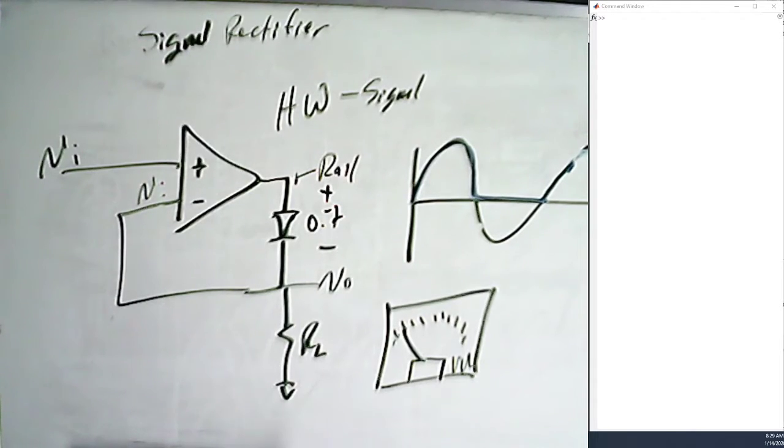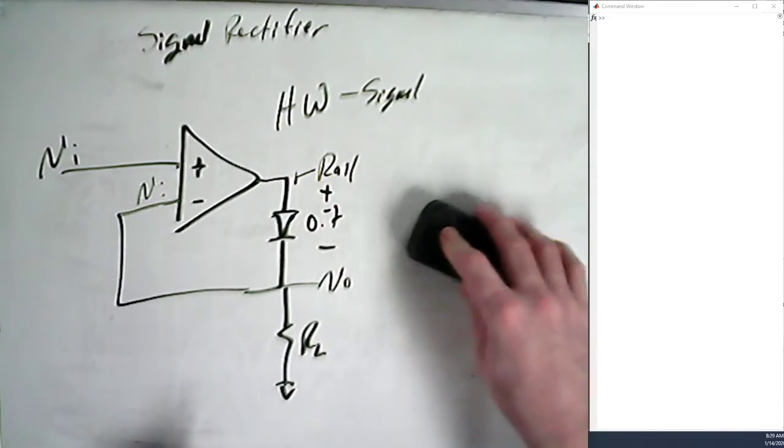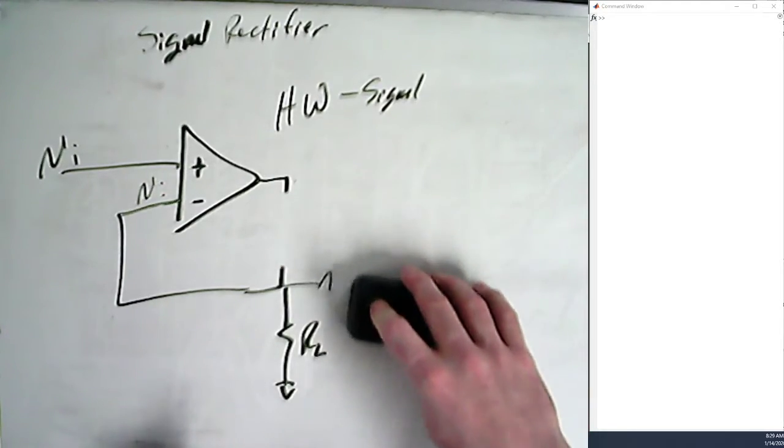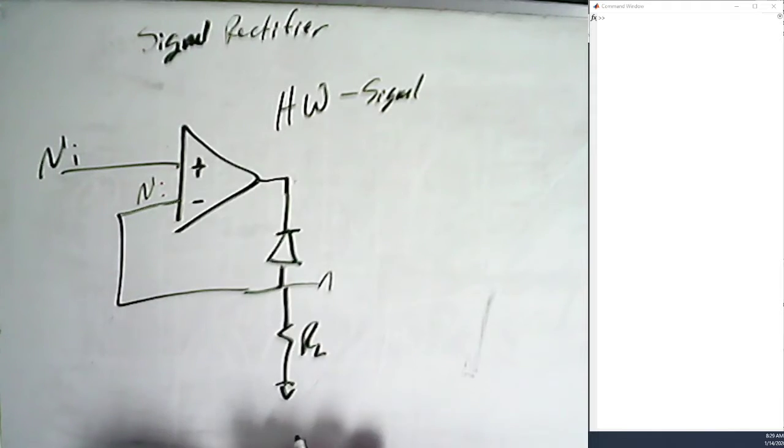And so you'd use something like this, throw it through a capacitor and an RC circuit for low pass to get this, so this does half-wave rectification perfectly. What if we want to do full-wave rectification? Well, let's talk about the negative first, and all I'm going to do, watch, I just flipped the diode the opposite way.